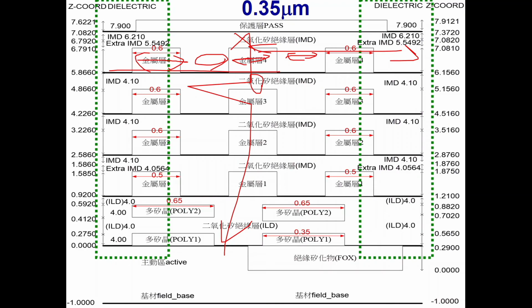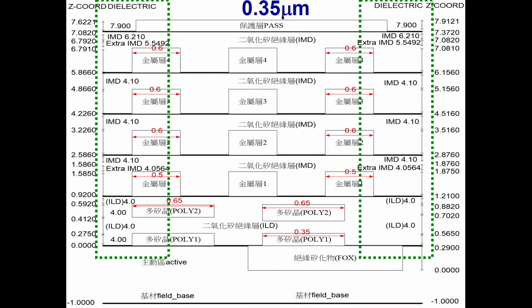If you reduce the thickness vertically, the resistance of the metal line will increase. If you reduce the spacing between the above and the below layers, then the parasitic capacitance will increase. It is really harmful for high frequency operation. Please keep this in mind. So in brief, the accuracy along the horizontal direction is much higher than in the vertical direction. Got it? That is the secret of TSMC and UMC.